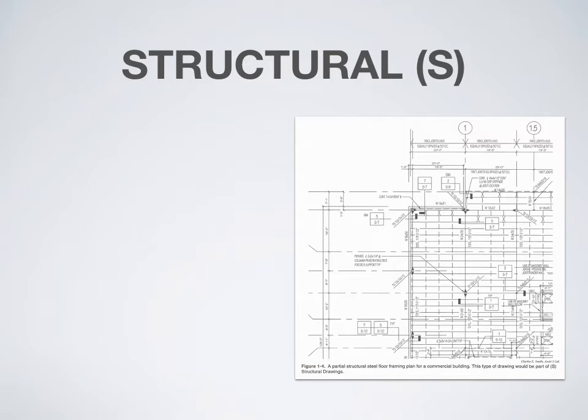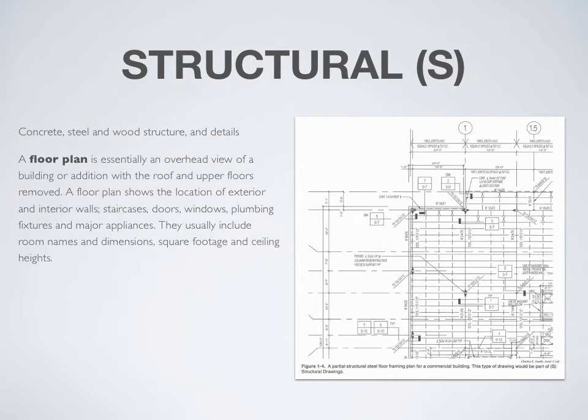Structural drawings, sometimes called the engineer set, label all of the structural members of a project, including structural steel, concrete columns or piers, engineered lumber sizing and types, and they also show us where each of these pieces can be located throughout the plan. You notice that there are lines that run through this drawing, creating a type of grid. These lines help indicate the exact spacing that structural members must be placed in order to achieve structural stability.